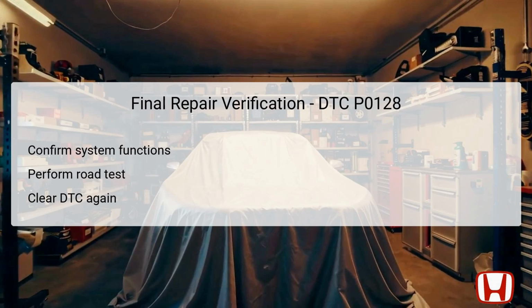After conducting these checks, it's essential to clear the DTC once more using the HDS to ensure that no issues persist. A successful road test and lack of subsequent DTC triggers underline the effectiveness of the repair and affirm that the cooling system is working as designed.